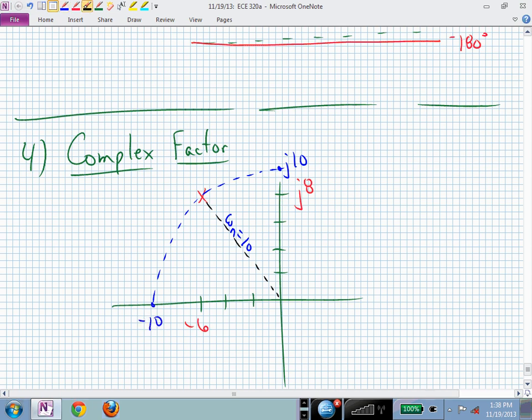And the values of zeta, this would be no damping. Remember, we're just sitting there oscillating. If we had a pole at j10 and it never dies, we have no e to the minus piece to that. Down here, we would be critically damped, right at the real line. We would have two poles at minus 10.